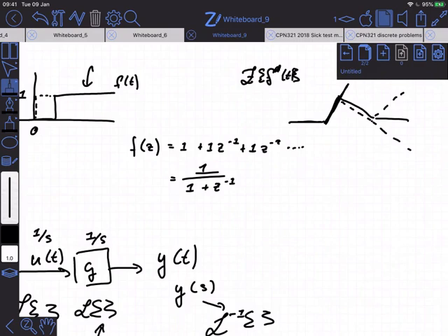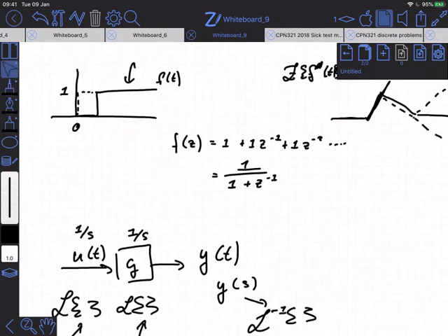We could also say that most discrete inputs can be seen as the sum of shifted inputs in the same way. Now, because of the sampling, there's a little problem about uniqueness, okay? Because remember, by the time we actually look at this signal, we're only looking at particular points. And so already we can see that there's not necessarily going to be a 100% unique description of that signal in terms of the building blocks.